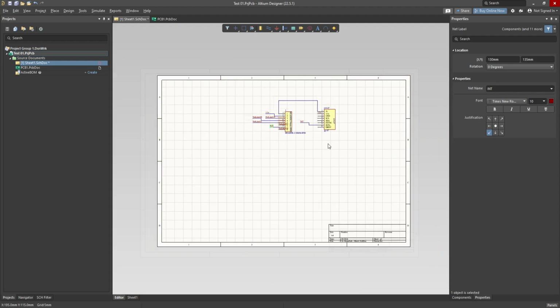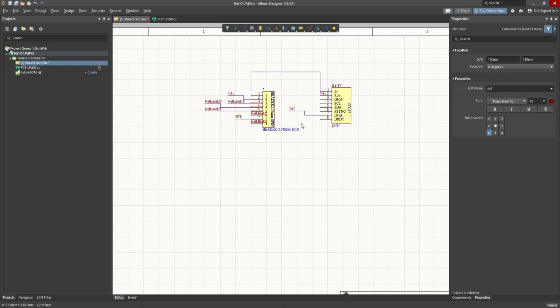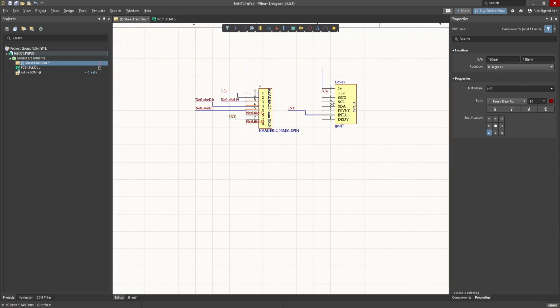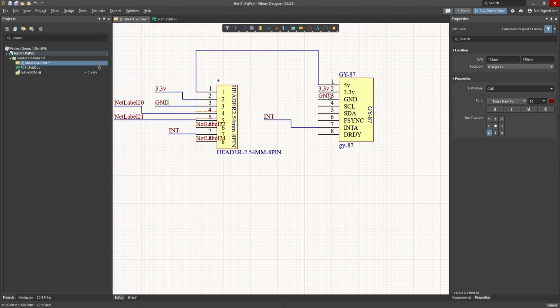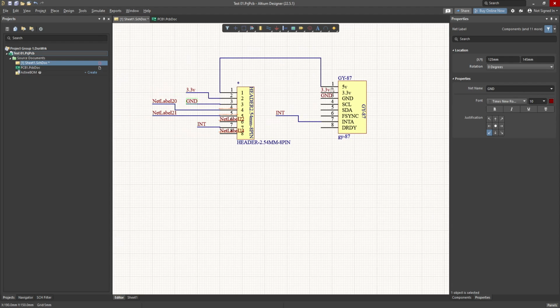So let's say I have made a few connections and I have a GND. Let's say GND is an important connection. So number 3 is the GND. And now if I copy and paste, this is my GND. Okay, so I have made 4 connections, pin number 1, 2, 3 and this interrupt pin, 1, 2, 3 and interrupt pin. I haven't connected any net labels like this one.